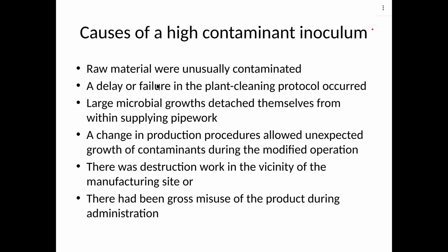And this is because if you leave the water to stagnate for some time, you may find that if you had microorganisms in that water, it's possible for the microorganism to colonize an area within the pipework, okay, and then multiply, okay, so that next time when you allow the water to flow, that colony detaches, okay, and it's possible for it to end up in your product, okay.